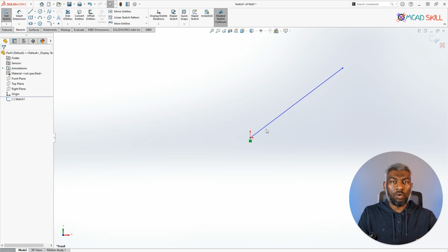So always keep in mind, whatever sketch you are going to design, always you have to start from center, because that's a fixed point. We are living in a 3D space, and now in this 3D space you need some constant, some starting point that will not move. Otherwise, if you leave everything floating, then you will not be able to control all models or any items precisely. That's why you have to start from a fixed point.